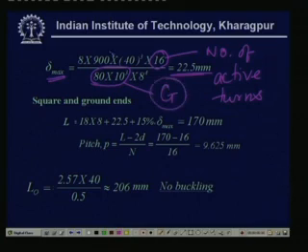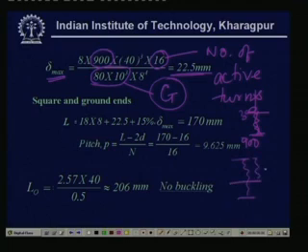Now, here you understand the load is 900 because the spring was squeezed from 300 to 900. This is 300, this is 900, it was squeezed in between. If you leave it, and then you put the entire 900, this comes out to be your delta max. So, it is under 900 that this is happening, and that delta max we are computing to be 22.5.